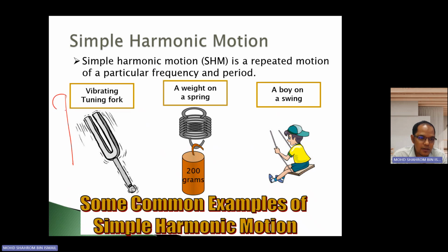Let's say this is a machine, rotating and shaking. To know if the machine is shaking severely or not, you bring a vibration tuning fork closer to the machine, and it also vibrates following the vibration of the machine itself. There are devices to measure how many decibels it goes, or how many hertz, that we need to know in order to inspect the machine.